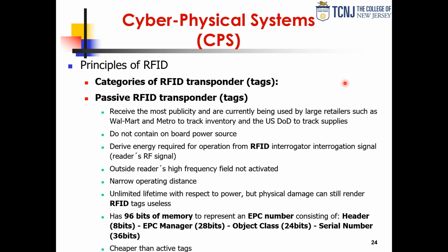And you can see hopefully how it is actually a must to get all these technologies talking to each other. So when you are in a specific frequency band and you are following a certain standard, you will get a specific message that has a specific format. And maybe that message is saying, identify yourself. So after that RF signal is demodulated and converted into digital data, the processor parses that command, it knows what the ID is, and then it turns on the transmitter and sends its ID.